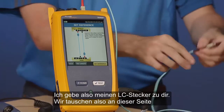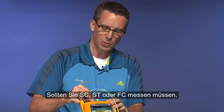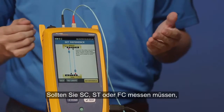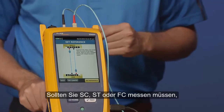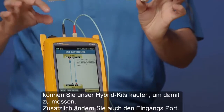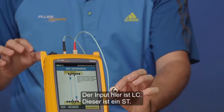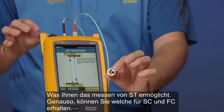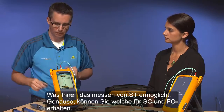So I'm going to hand my LC connection to you. We'll do a swap at this end and we'll place them onto the input ports. This is LC out of the box with the CertiFiber Pro. If you have a need to do SC testing or ST or FC, you can buy your hybrid kits to do that. And in addition, you would change out the inputs. So the inputs here are LC, this one is an ST, and that would allow you to do ST testing. Likewise, you can get one of these for SC and FC as well.